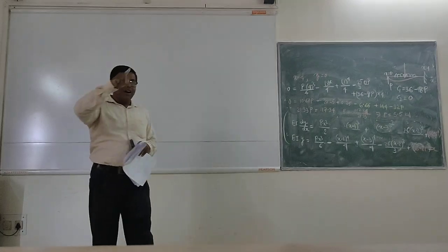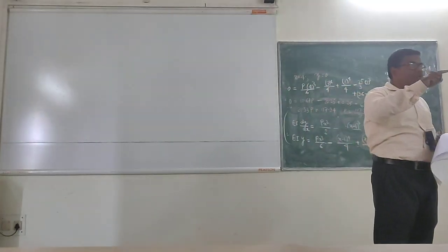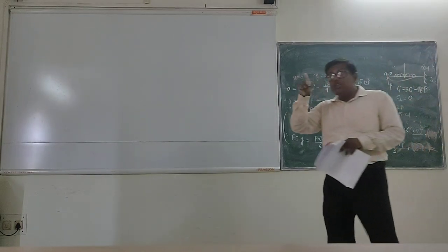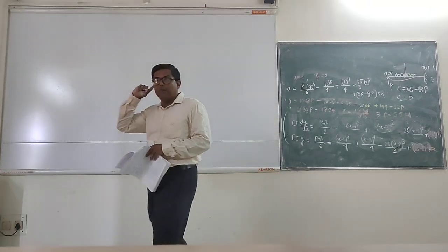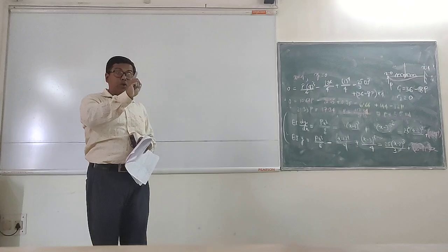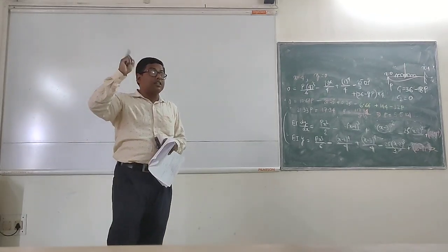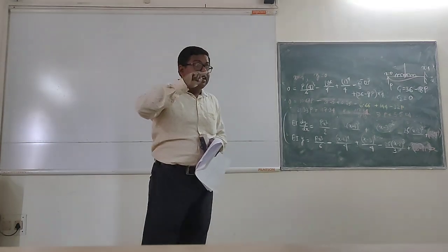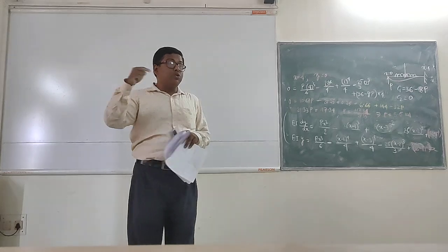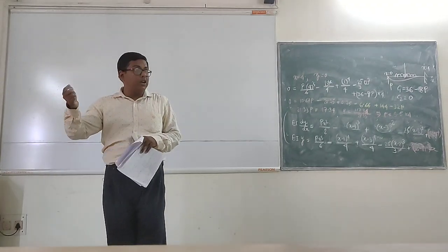So you see how beautifully the deflection equation is being used to find out the indeterminate reaction component of a structure. That is the task of this problem: to understand that while solving indeterminate structures, which you will learn in your 5th semester, the deflection equation is not only in double integration. You will learn many other methods like the conjugate beam method, moment area theorem, then Castigliano's method.